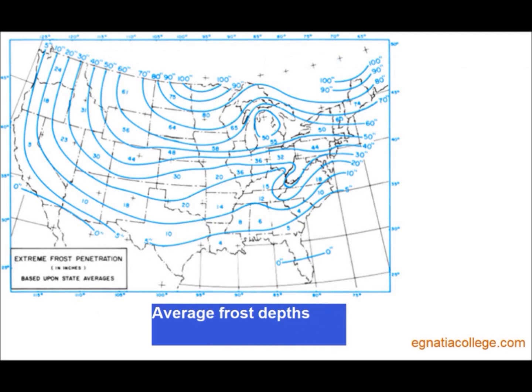Depth of footings. In many sections of North America, the moisture in the surface of the earth freezes in the winter. As this frost forms, it causes the earth to expand. The force of this expansion is so great that if the earth under the footing of a building is allowed to freeze, it either cracks the footing or moves the building. To eliminate this problem, the footing is always placed below the depth of any possible freezing. This depth is called the frost line. The local building department will have specific footing depth requirements for their area.